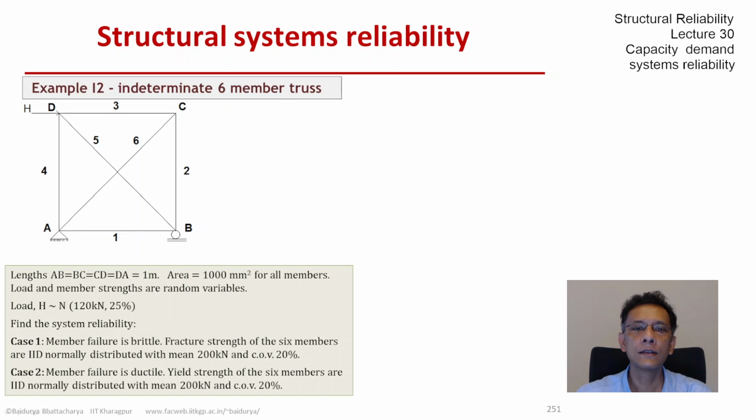After the 2-unit parallel configuration, let us look at a slightly more complicated structural system: a 1 degree statically indeterminate truss structure, as you see on the screen. This system has 6 members, and as we know very well, given the boundary conditions it has, this is 1 degree statically indeterminate. We can verify this: if 2 elements fail, then this system becomes unstable.